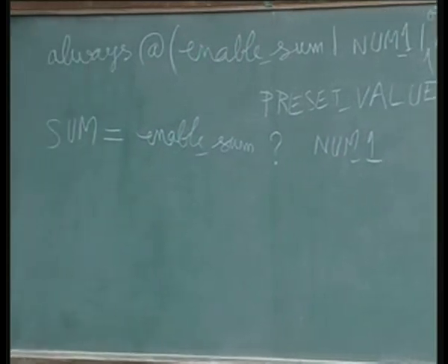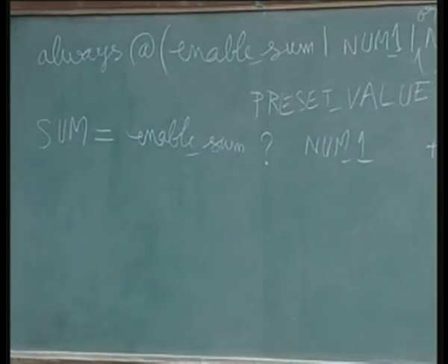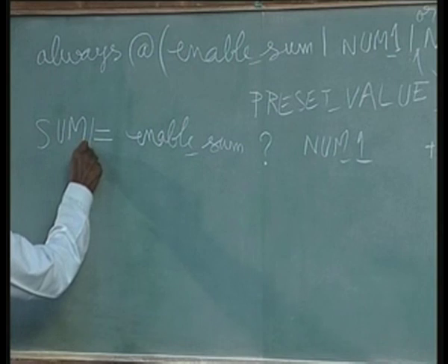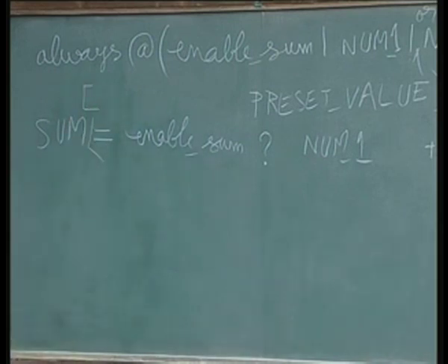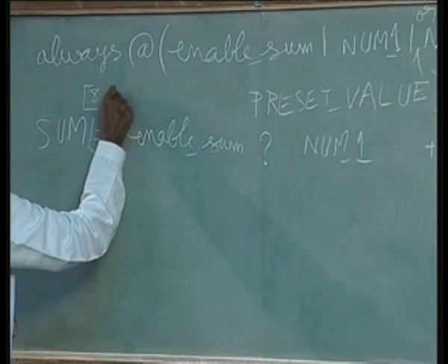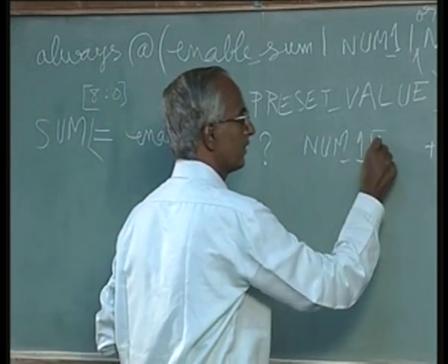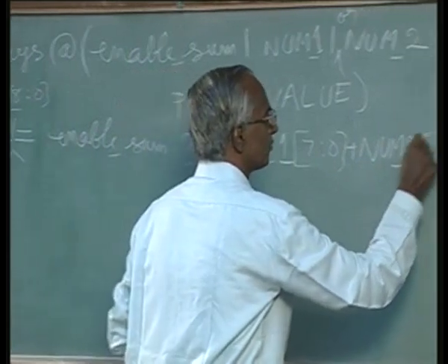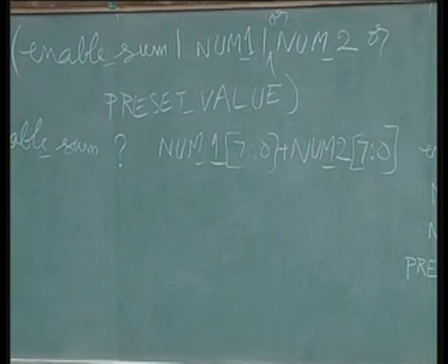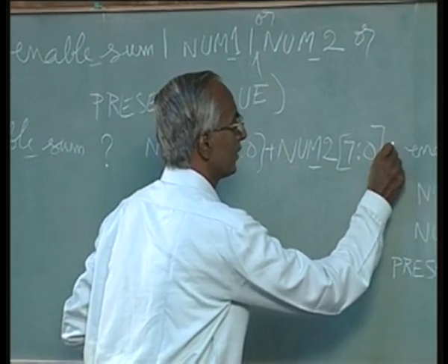Do you think this statement will work? We have not put the precision, it will still work, and we can also specify the precision here, which is normally done by all designers, because we do not have to wade through previous code and find out what precision it is. So, in this statement, we can identify that by just mentioning the range, say for example 7 to 0 and so on. Will this statement still work? It will not, because we have not terminated it with a semicolon here.